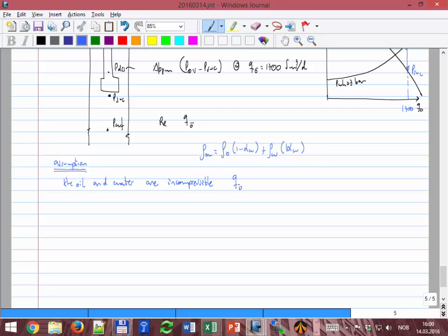That means that the rate of oil measured at the surface is equal to the local volume rate at any P and T, okay, and also the water. And this is usually a bad approximation, but it's not so bad for this heavy oil with low GOR systems, okay. But there is all the time some gas coming out of solution that causes the rates to be different, okay.